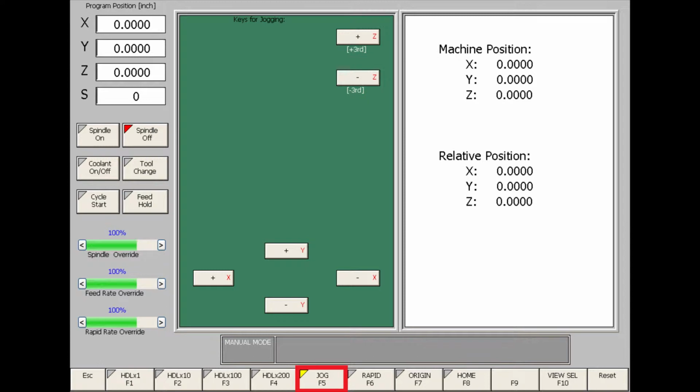You can also jog the machine in manual mode by selecting the appropriate jog function. The times 1, 10, and 100 correspond to jog speed. Then, jog using the hand wheel or jog keys. You can also change the current tool of the machine by using the keys for next tool and previous tool. Once the machine is homed, go back to the main menu.